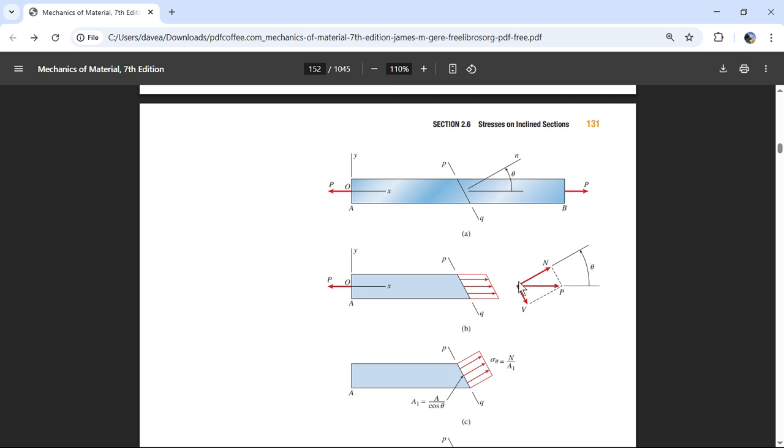But we said that shear can only take half the load. So if this is a 1-inch steel bar, with cross-sectional area, and I'm pulling 58,000 pounds in tension, let's say it can take 58,000 pounds in tension. But it can only take 29,000 pounds in shear.